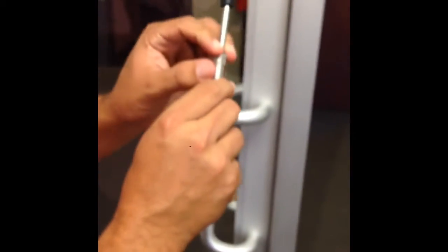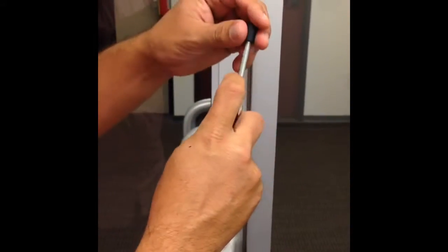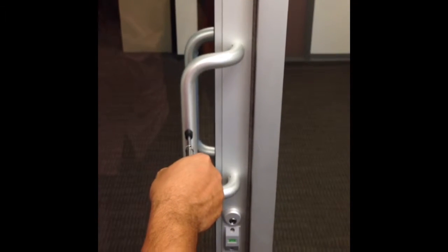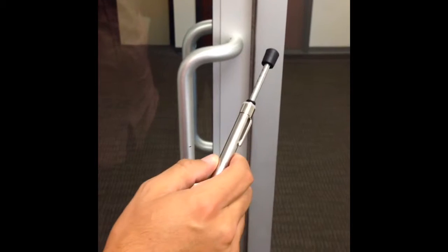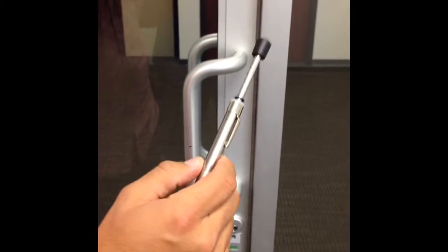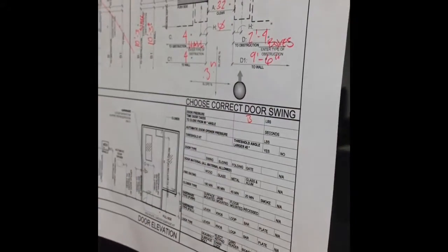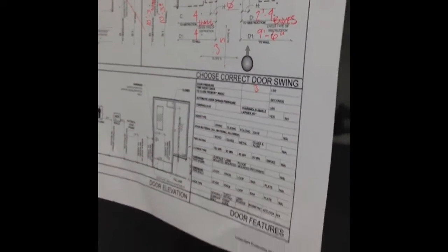I'm going to do it one more time just so you guys can get the gist of what we're doing here. Again, we're going to move the ring all the way down to the bottom, go to the center of the handrail, and push until the door opens. Do not jam it. As you notice, it was a nice gentle push that I used. So from there, you'll see the door pressure, and this is about 3 pounds. And then we'll go to the next step, which is the time the door takes to close.